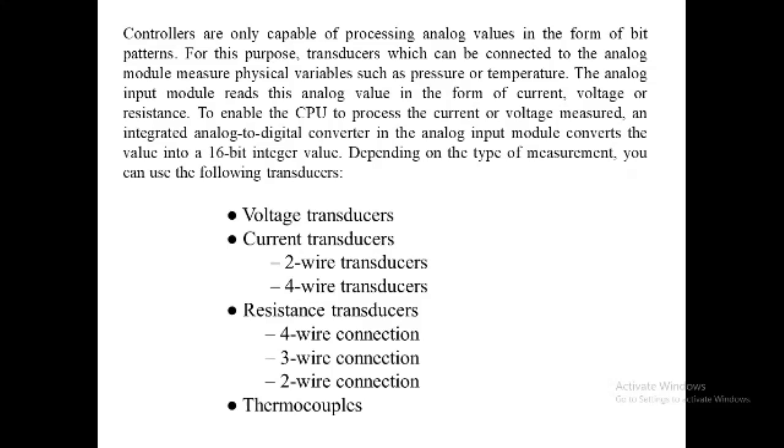Important parameters of these analog modules are the types and range of the measurement. The precision, resolution, and conversion time are the main points to consider when selecting an analog module, and for some applications, such as a system which covers a large area, common mode or channel isolation are also important. The parameters listed here are examined in more detail. Some precision and resolution values are considered.